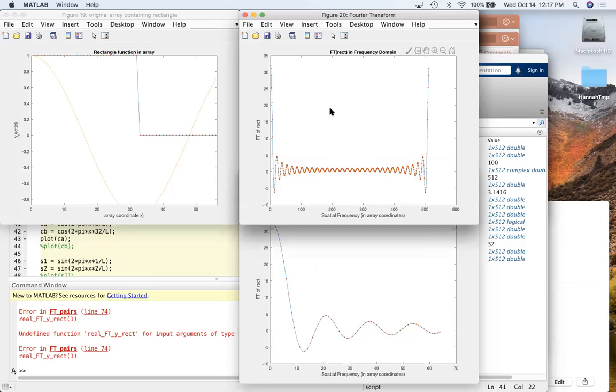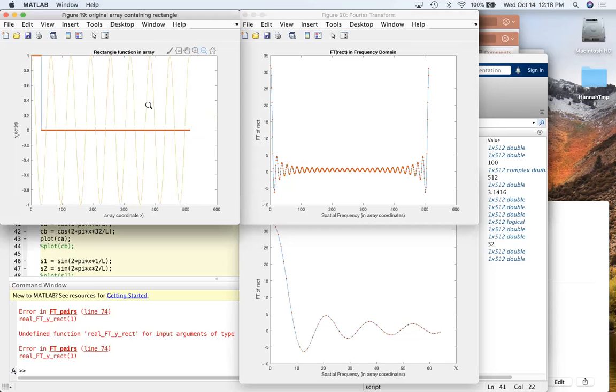And so that's an underlying representation of the fact that our sampling rate here is such that we can adequately represent frequencies out to here, out to half of the array length, because the cosine wave that produces a 1 up, 1 down, 1 up, 1 down is in fact 256 cycles over the full field of view. And so that's why we're seeing this function. It's accurate to here, and then it's just a replicant of itself going out to these higher frequencies.